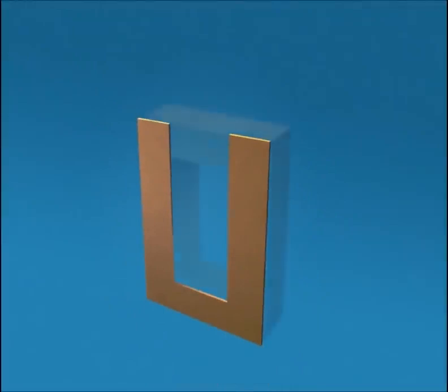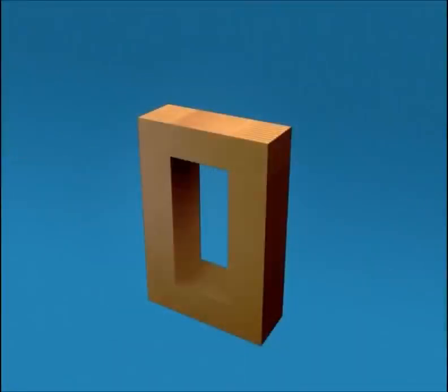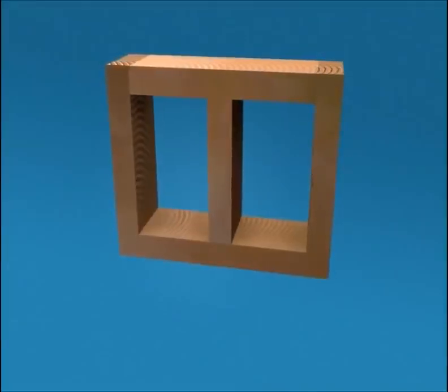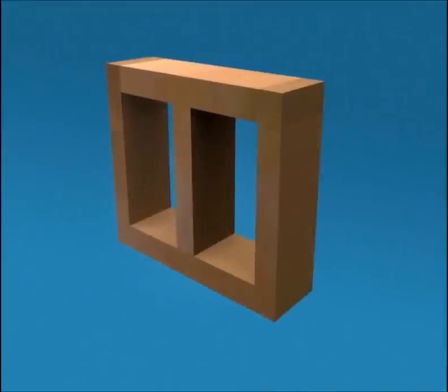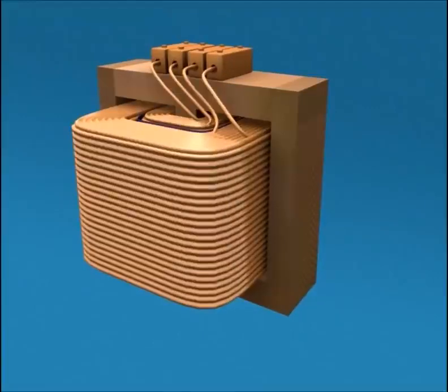The problem with the construction discussed so far is that the two windings are well separated from each other and there is considerable reduction of magnetic coupling and hence the efficiency of the transformer. This disadvantage can be overcome by constructing the core like this, in which the two windings are brought close to each other, thereby improving magnetic coupling between them.